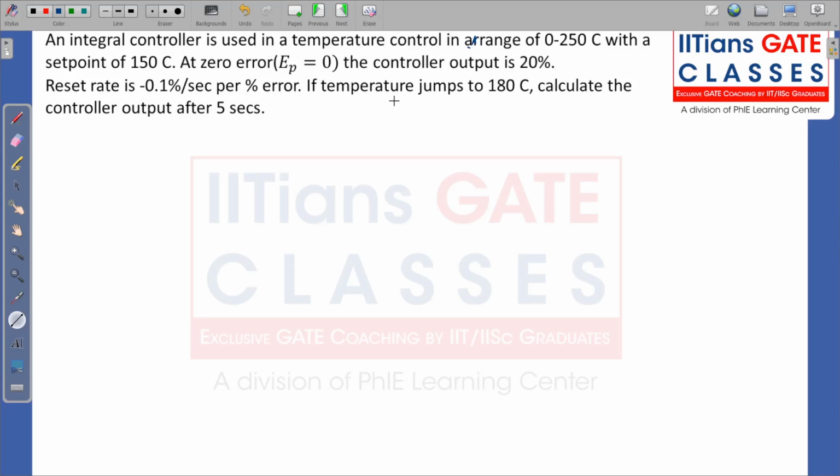So here set point given is 150 and my actual output is 180 degrees. We know that P of T is equal to Ki into E into T plus P naught. Ki given over here, reset rate, is minus 0.1. Error we don't know. Time is 5 seconds, plus P naught, which is given as 20%. We need to calculate the controller output in percentage. So if we find out this E, we will be able to solve it. So let us try to find out E.